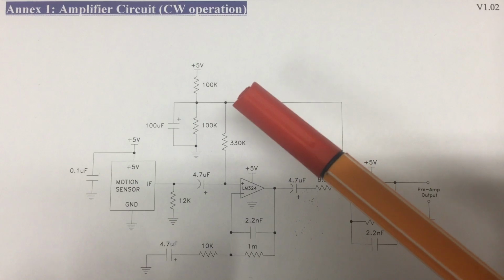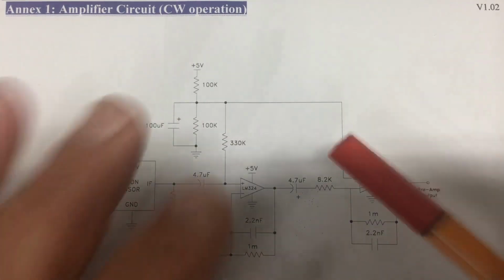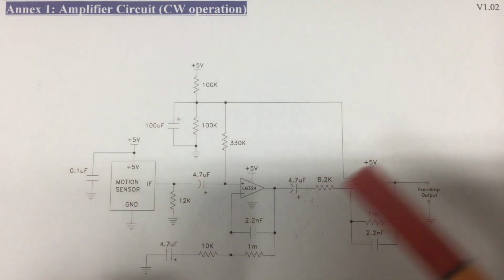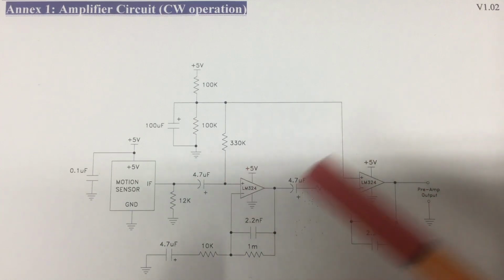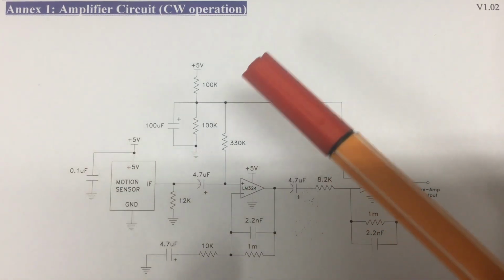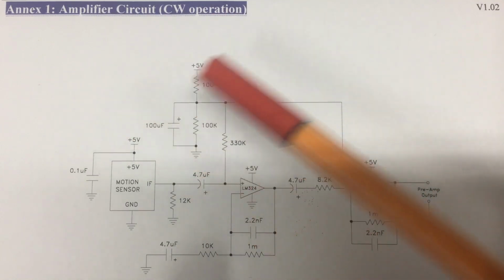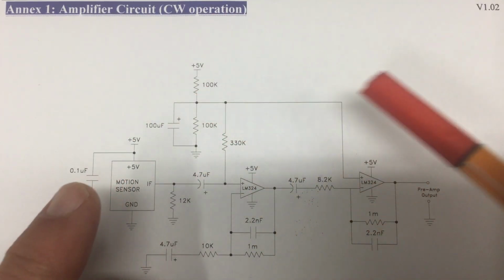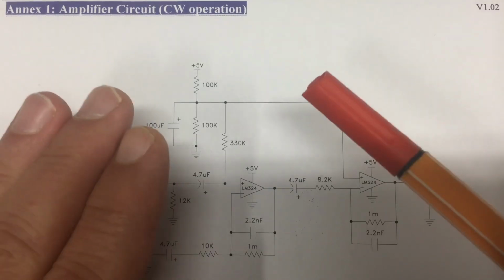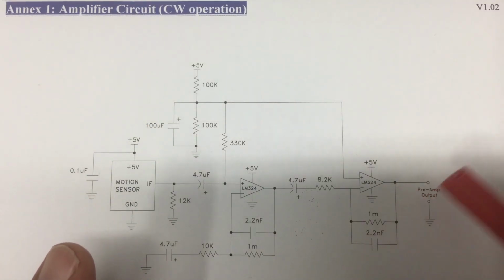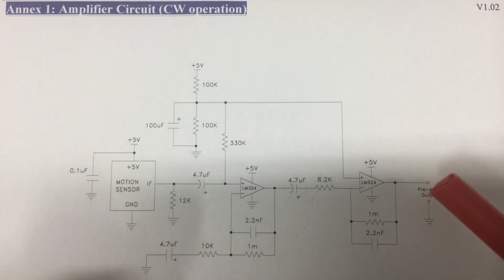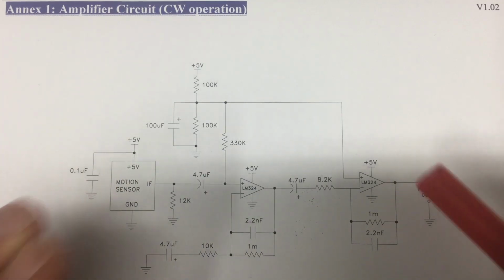That 330K resistor, the same value. However, Limpkin is using a much better operational amplifier. And he beefed up the power supply rails and that half VCC rail considerably. And he added that peak detector and, of course, the comparator at the output.